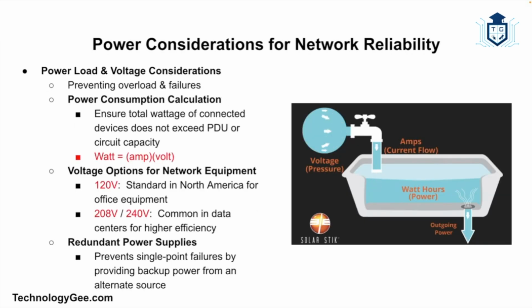Next, we have power load and voltage considerations. Understanding power loads and voltage requirements ensures equipment runs efficiently without risk of overload or failure. So you want to calculate power consumption, which is the total wattage of connected devices that must not exceed the PDU or circuit capacity.